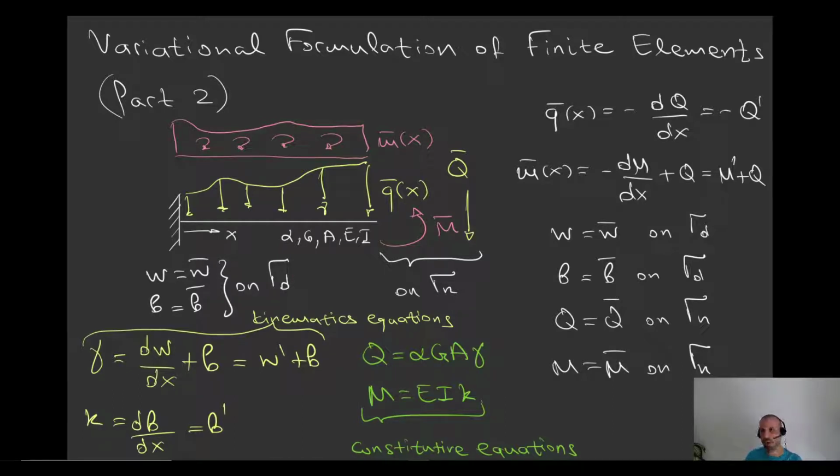And please recall the primal unknowns of the problem are the vertical deflection indicated here, denoted by W, and the cross-sectional rotation beta. Whereas in another portion of the boundary, which we call gamma n, which is actually the natural boundary, we can apply conditions based on load. So basically applying loads on this corresponding boundary of the problem. And these loads can be in terms of vertical forces, Q bar in this case with capital, or bending moments, which are indicated here with the M bar.